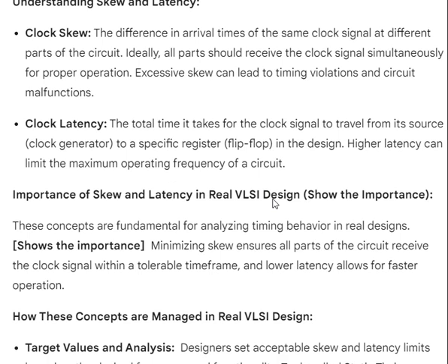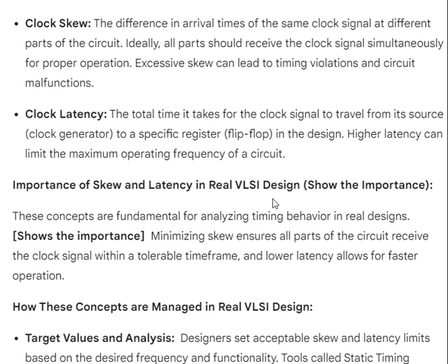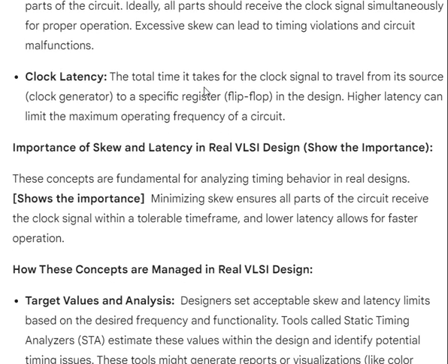Understanding skew and latency. Clock skew. The difference in arrival times of the same clock signal at different parts of the circuit. Ideally, all parts should receive the clock signal simultaneously for proper operation. Excessive skew can lead to timing violations and circuit malfunctions.